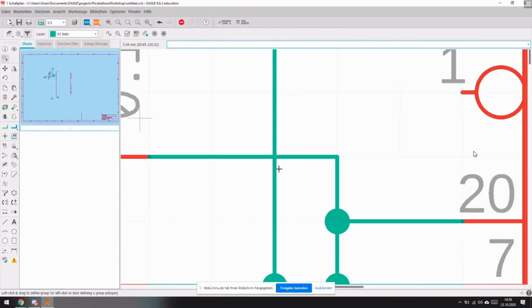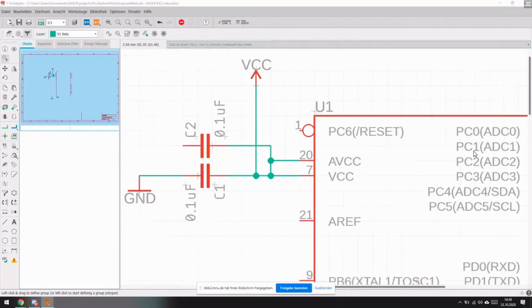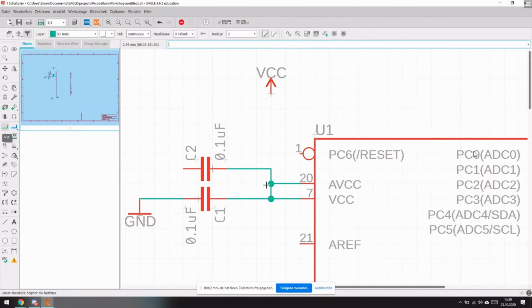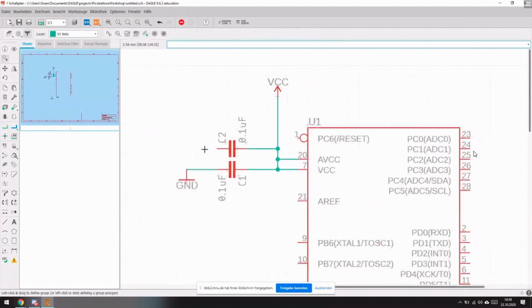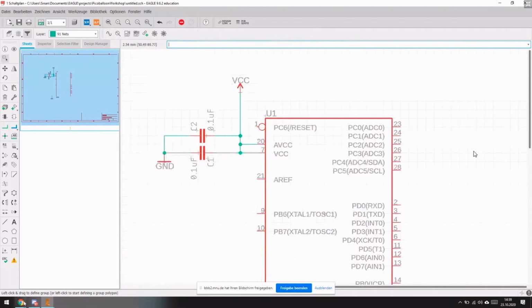Like they are, but just looking at the schematic, they are not, because there's not a junction. Okay, we can just tidy that up by just moving this component here, deleting this line, just doing another net here. Now it looks much cleaner. And we also have to connect the ground to the capacitor. Just like that.